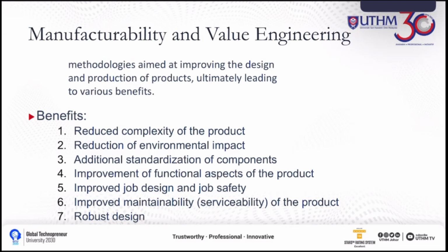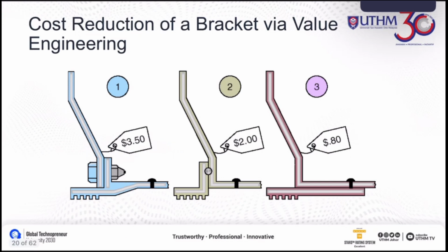Okay, let's say you have a trial of your product. So you see there is room for improvement in your design. So maybe you change the element or the component in your design to make it simpler, for assembly, for example. So that is what we call value engineering. Here is an example. In the first phase of the design, it's a more complicated assembly. You need to put screws here, and the cost is very high, which is $3.50.